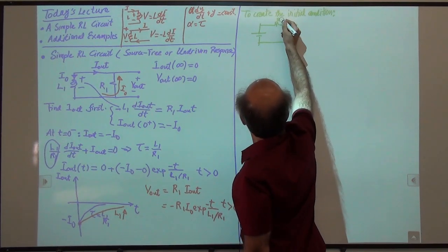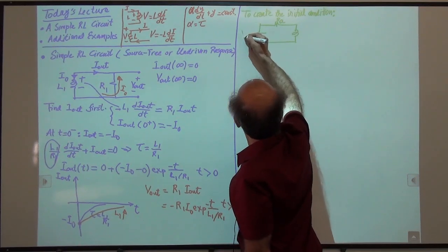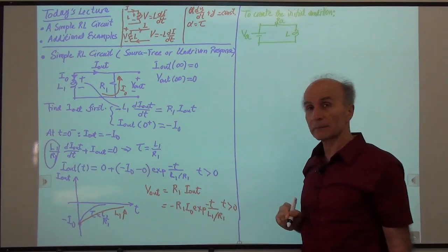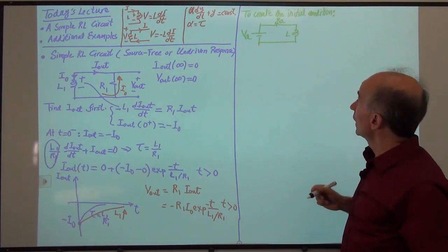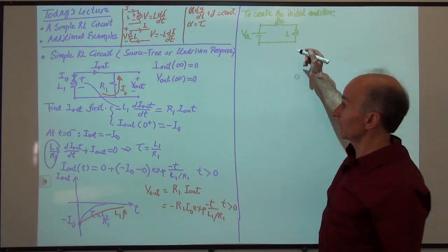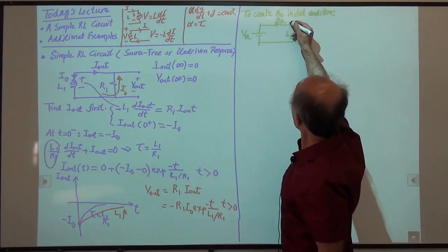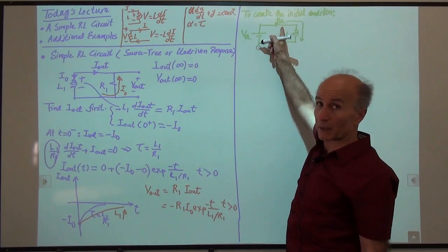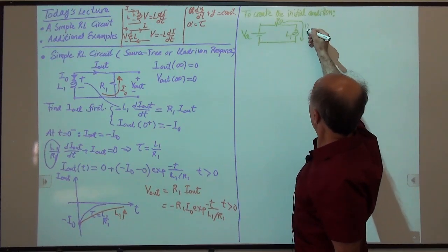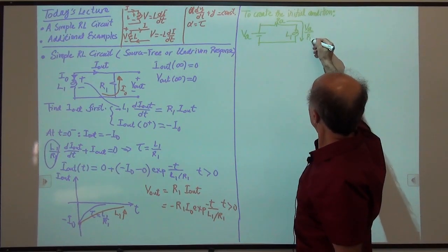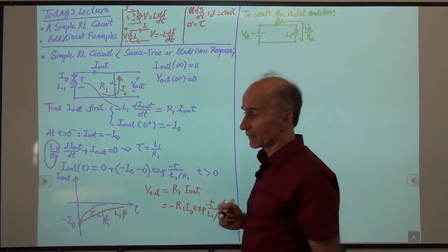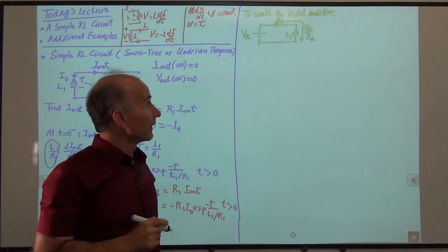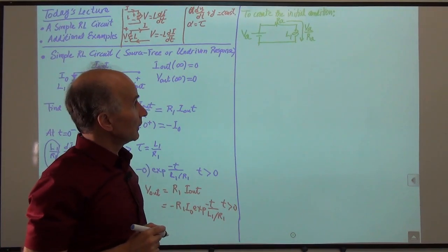So here's RA, here's VA, and here's our inductor. You can see that if I let the circuit go for a long time, a current is created in this loop, which is given by VA over RA. Remember we calculated this last time? So using this topology, I can create the current that I need, and then I let the circuit go.